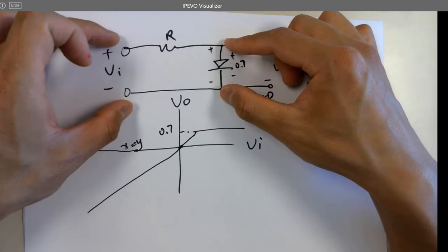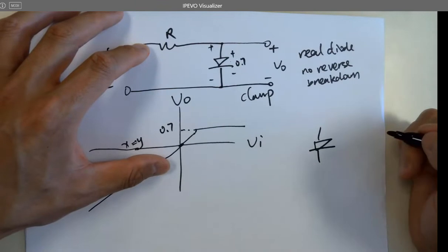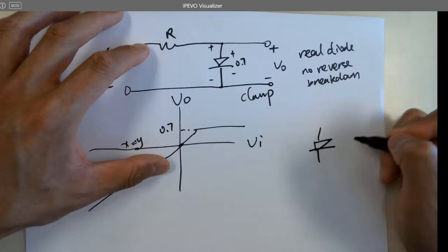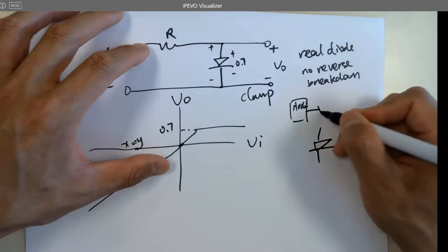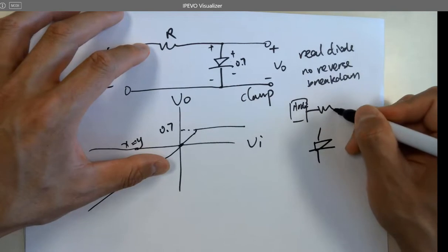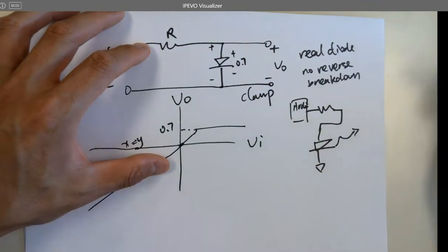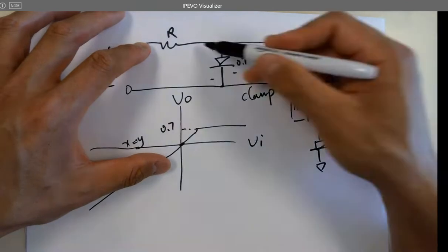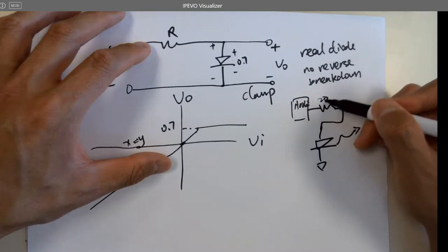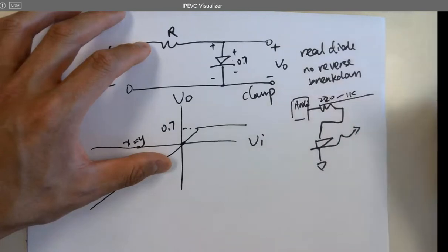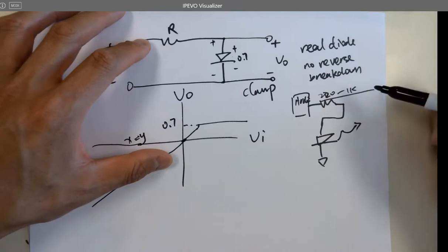That's why for the LED, a light emitting diode, right? Still a diode. How to operate it? You got your Arduino here, right? Have a pin. I always have a resistor here connected to this guy and ground, right? So you can operate it, turn it on, or blink it. You always need a resistor for that reason. And you don't need a very high resistor here. You just need usually 220 ohms to 1K ohms, that range. Depends on how bright you want this LED to be. But a couple hundred ohms will be good enough.